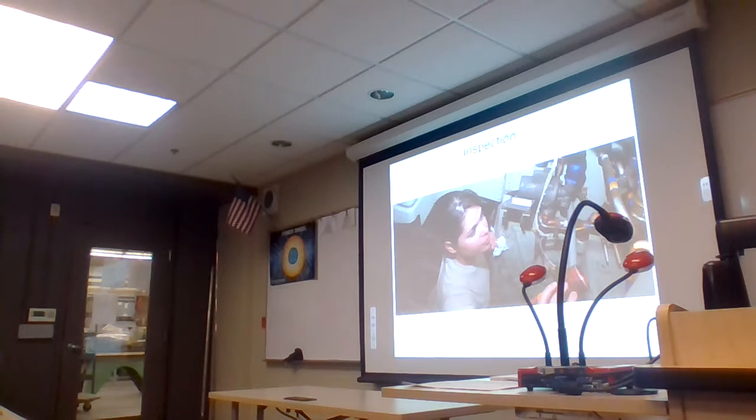And here's an example of inspection. Maybe one piece of equipment missing from that lady's eyes, but maybe some safety glasses. But you can see that inspection pretty much is relegated to looking for leaks, looking for correct routing, looking for chafing on lines, looking for maybe routing of electrical wiring that goes to some of the other components that are there. And she looks like she's got a cleaning cloth at the ready to clean up leaks. Pretty simple.